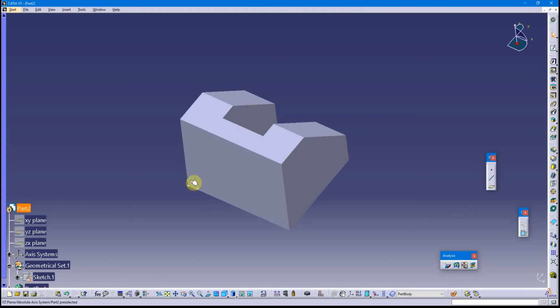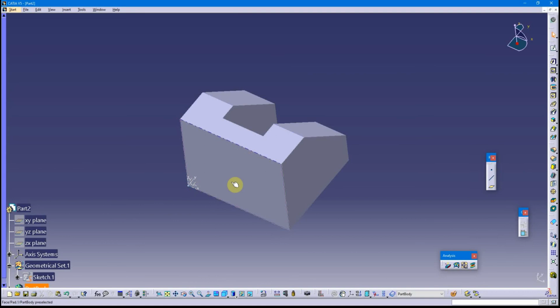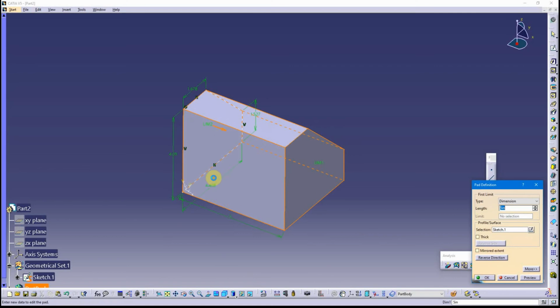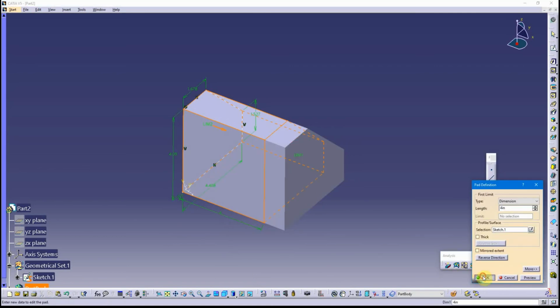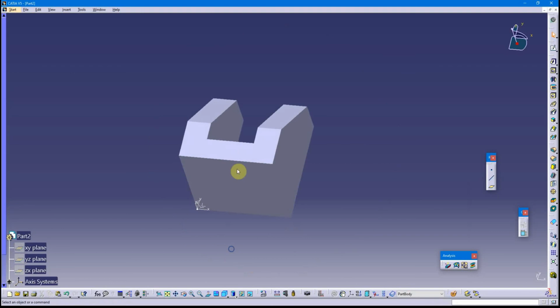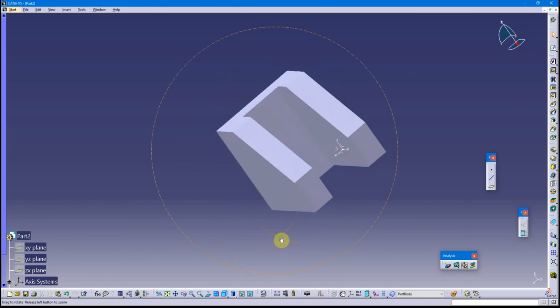Specifically, if I were to put this in the center, put a reference plane in the center, now mirrored extent would have given me 2 inches and 2 inches when I had the original 4. I wanted a very intentional 4 inch dimension. Change this back to 4. So I did a 1 direction extrusion, and then I centered the pocket up to capture that design intent. I hope this helps.